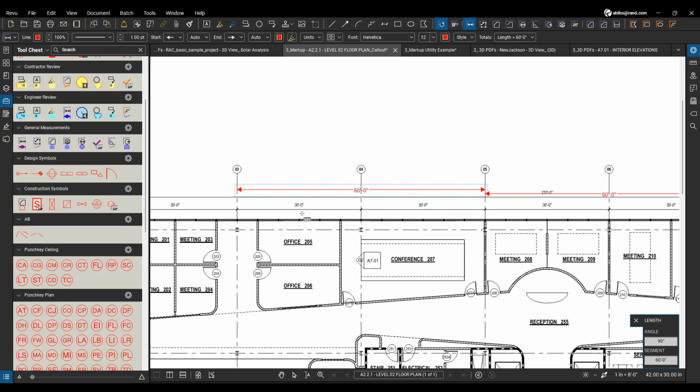And then Bluebeam Review also has a lovely tool for documents that are created without a scale, where you can take a known dimension. So if the scale didn't come in on this, we can associate that known dimension, that 30 feet. We just put a little tool on it, boom, boom, and we tell it that's 30 feet. It puts it to scale automatically for us. And even for those documents that you maybe took a picture of at the archive down at the city or county office, took a picture on your iPhone, that's the document that you have.